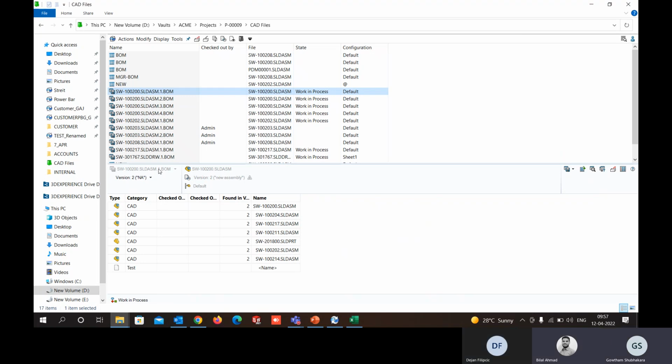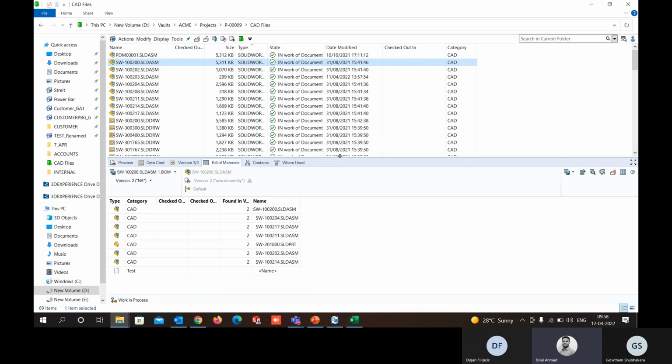Gautam, yeah. I think just to explain, correct me if I'm wrong, but just to put it very simply, we have parts in an assembly. And each part, for example, if it needs to be cut on a certain machine, we model it purely from a design perspective in SolidWorks. And then we will create a DXF file that we would be sending to the machine.